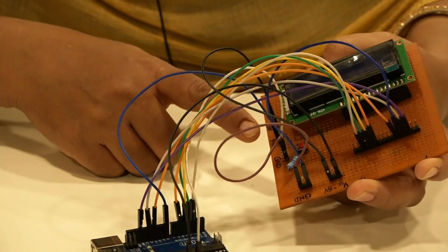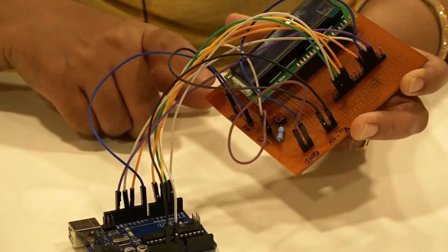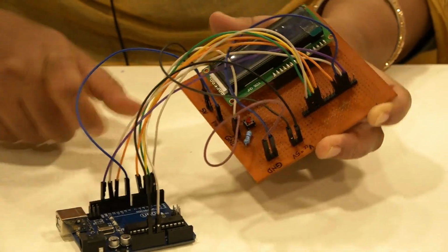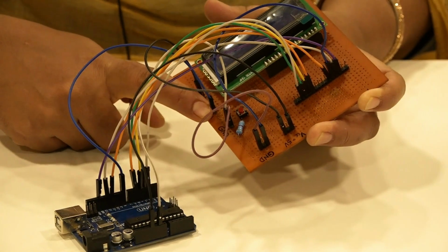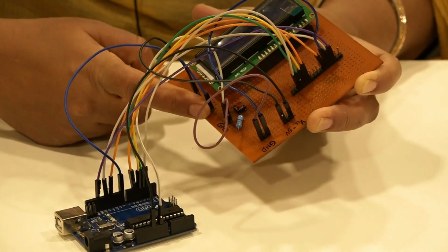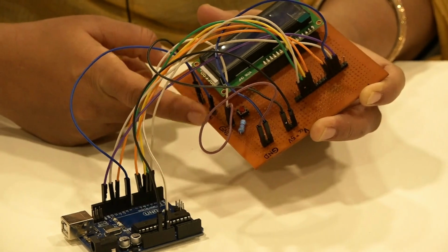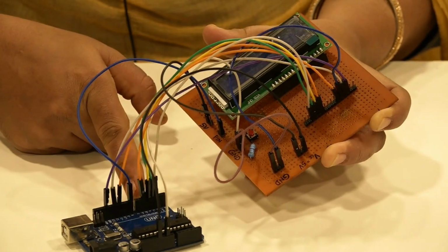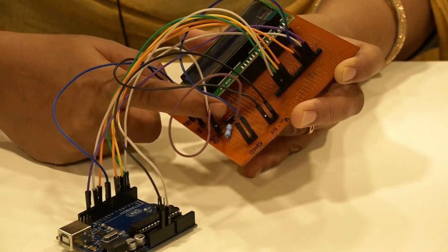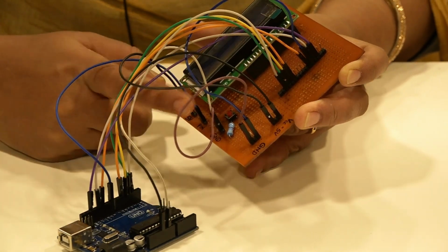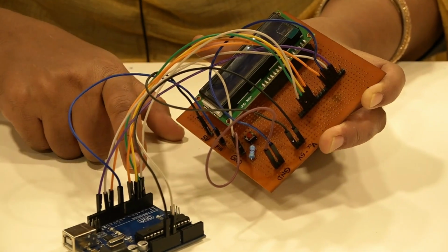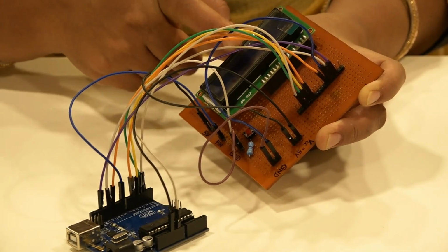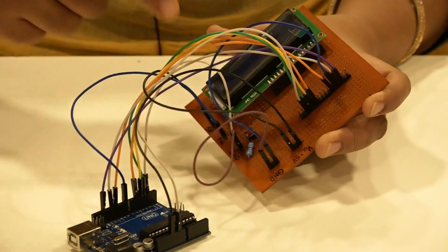Here you give 5 volts from the Arduino board's VCC pin or Vin to the push button, and then you have pin number 8. If you see in the sessions or in the PPTs, this is the 8th pin. As I said earlier, the 8th pin is not compulsory. You can take any digital pin as the input. The input here is whenever we press the push button, one number will be generated randomly. Whatever number is read will be displayed onto the LCD, either 1, 2, 3, 4, like that. So, these are the connections.